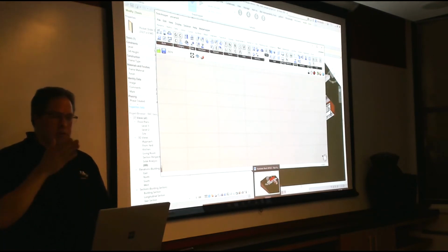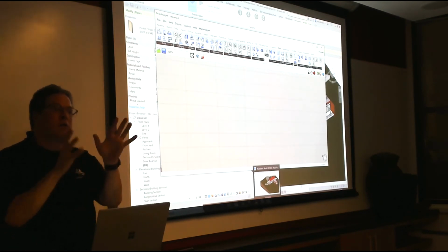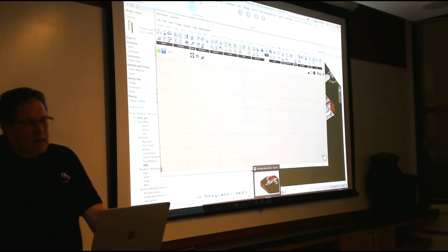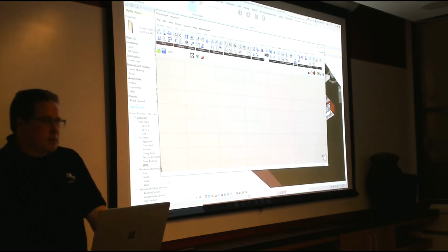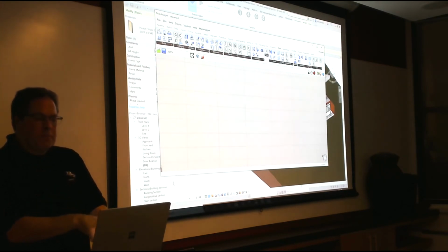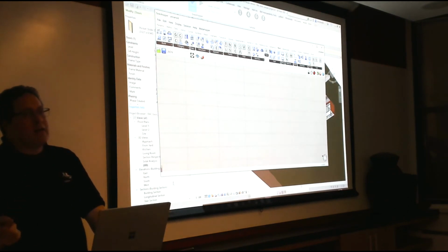What we might do is a data dam in Grasshopper, and then you say, okay, now go. You'd have to look at the timing internally. I've found, especially with adaptive components, timing becomes important because it can take a while to populate them. Once you populate the adaptive components in Revit, they will preview in Grasshopper, in Rhino. Therefore, if you wanted to, you could have a bake feature that bakes the adaptive component geometry back into Rhino. So you could do that.